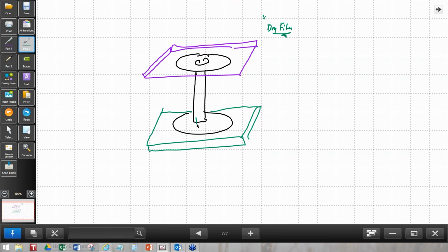Well, there's only a couple of ways. One is to completely plug the hole of the via at an appropriate time. Before you actually put any masks on, you jam all that epoxy down in it and make sure it's completely plugged and sanded off flush. And then when you go over and tent it, there'll be no actual volume that the moisture could get in. So that's a really good thing to do, but it's a pricey and difficult and time-consuming thing to do. So most people don't do that.